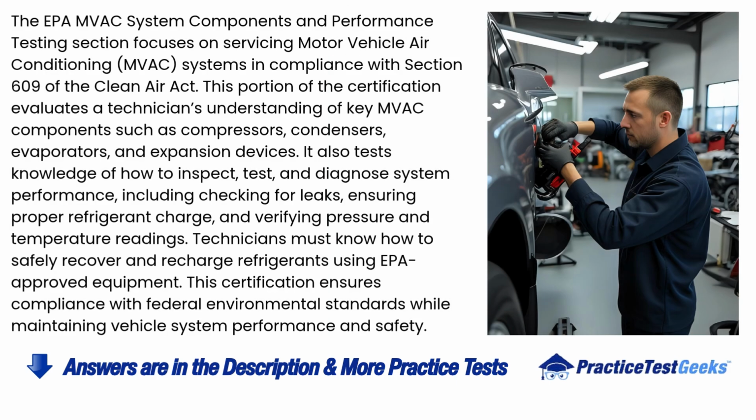The EPA MVAC system components and performance testing section focuses on servicing motor vehicle air conditioning (MVAC) systems in compliance with Section 609 of the Clean Air Act. This portion of the certification evaluates the technician's understanding of key MVAC components such as compressors, condensers, evaporators, and expansion devices. It also tests knowledge of how to inspect, test, and diagnose system performance, including checking for leaks, ensuring proper refrigerant charge, and verifying pressure and temperature readings.